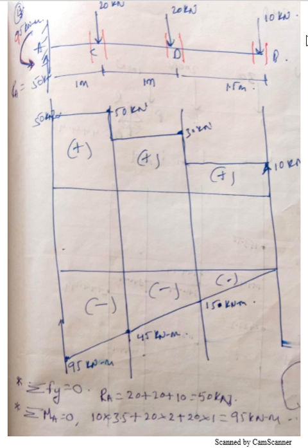Now consider this force coming from the right side. This force is trying to bend the beam downward with respect to this section, so it is minus 10 into the perpendicular distance of 1.5. Minus 10 into 1.5 will give me minus 15 kilonewton meter. So from here I am joining using a straight line because it is a point load, minus 15 kilonewton meter.